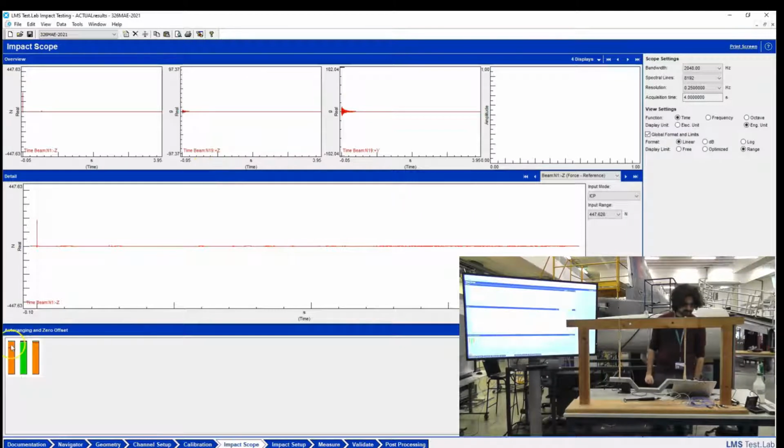Now what you have here, these colored bars, these ones are the ranges. So I told you what we need is amplification. This box is capable of recording with a resolution of 24 bits. That means you have two to the power of 24 levels at which your signal can live.